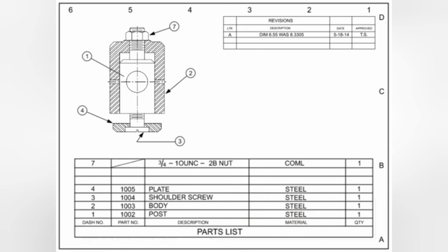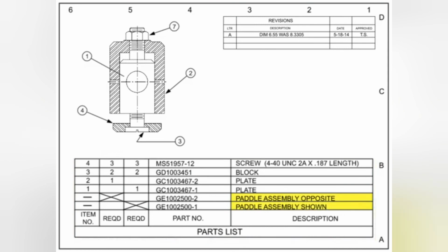Most modern drawing standards also require a dash number, which helps locate the part in the field of the drawing. This item number is referenced both in the parts list and in the field of the drawing to identify the part. Other useful information typically found in the parts list are material, material specs, heat treatment requirements, size, weight, flag note indicators, and finishing processes. For drawings that show multiple configurations of an assembly, additional columns indicate the quantities of subcomponents that make up each assembly.